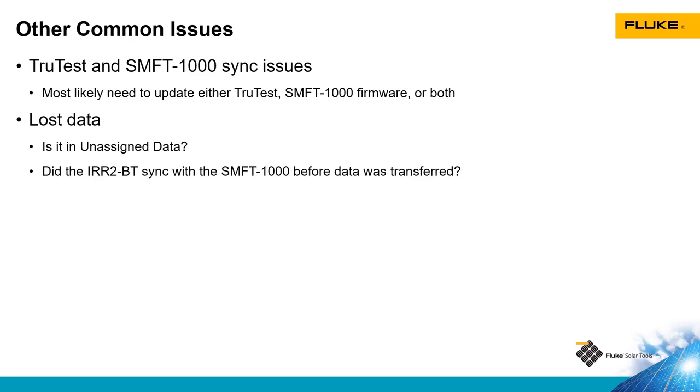Synchronizing the clocks allows the SMFT1000, if it loses connection to the IRR2, once you regain connection, it will synchronize that data. So it will import the irradiance and temperature data from the IRR2 into the SMFT1000, and it will correlate the data together to get the proper irradiance and temperature data matched with your test results.